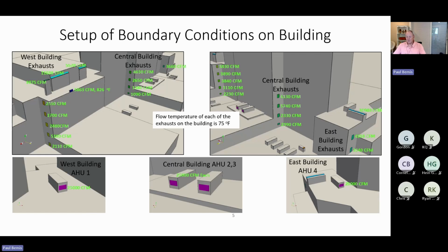So first you must set up the building. Often the building can come from a variety of sources. If you have a CAD model of the building, that's great. We've gotten pretty good at being able to take a Google Earth image and transcribe it into geometry as well. So even a location of a building is good if someone can identify where the inlets and outlets are. And most importantly, we need to know what the magnitude of these devices are.